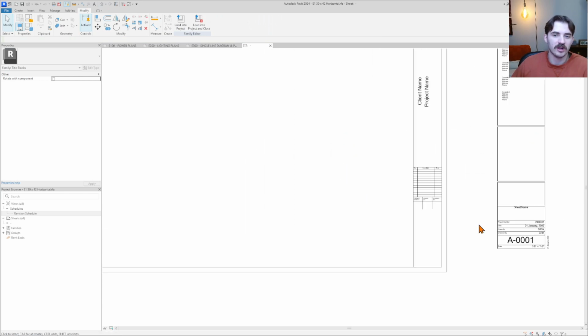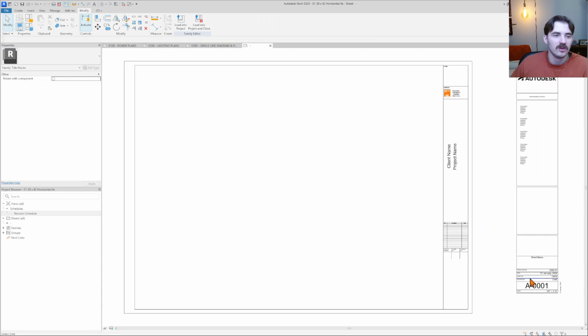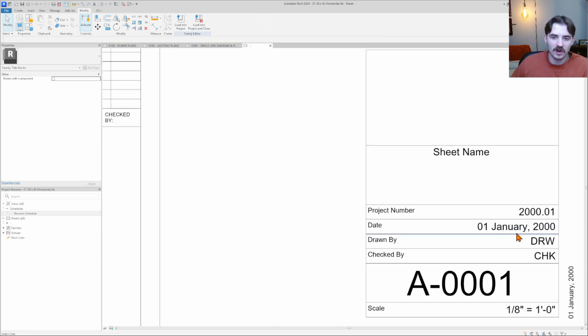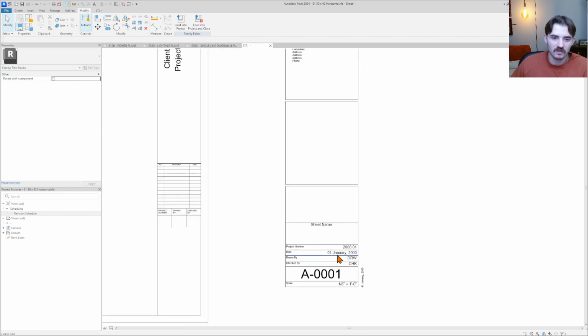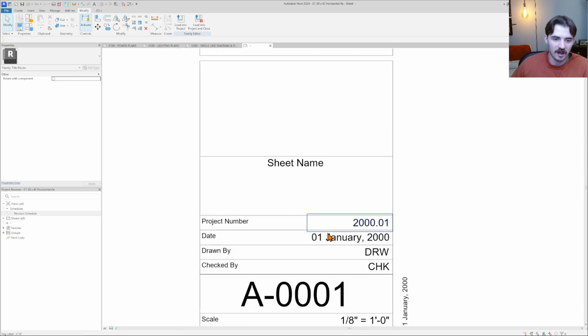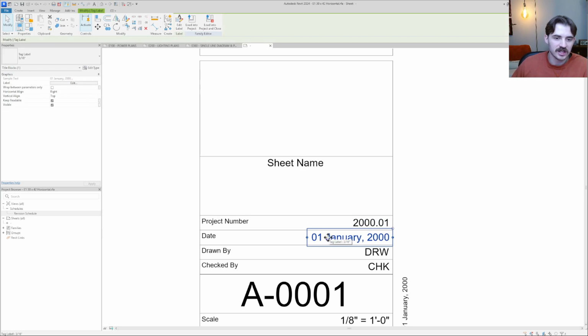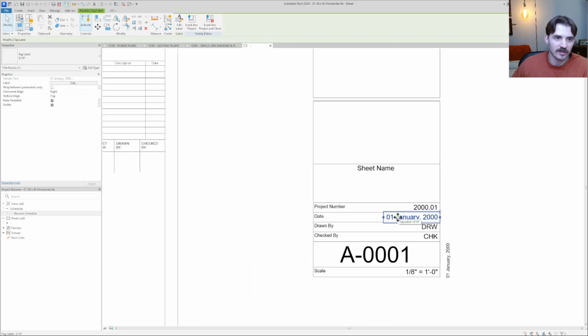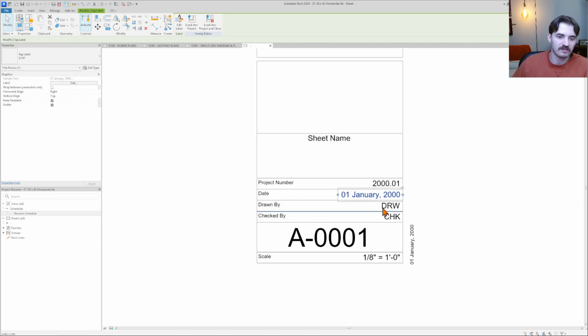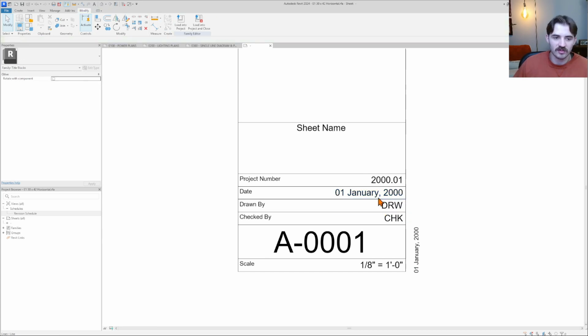All right, here's an important technical thing with Revit. What Autodesk has done with their title block has been to set up labels. These are things that are related to system parameters. When you create any type of title block, there are these things called system parameters that will be associated with every single title block and sheet. And the Autodesk title block has already linked these to some of those system parameters.